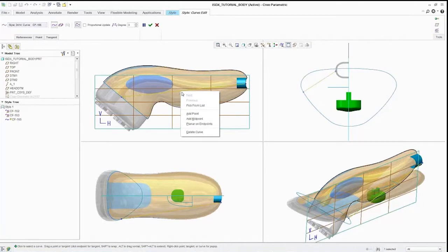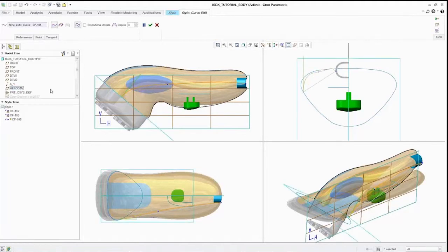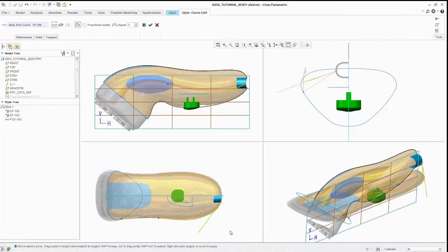I make a little tweak in one of the views and I have it drive in the other views as well, so I can make sure that I'm really getting a good curve all the way around, being able to design in a true 3D space. I also make sure that I don't have any very glaring mistakes. Again, sometimes doing a 2D curve in a 3D space, things don't turn out exactly as you will, but with a 4-panel view, you really can't go wrong.